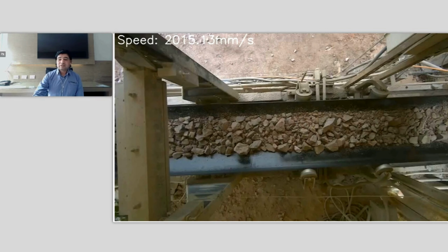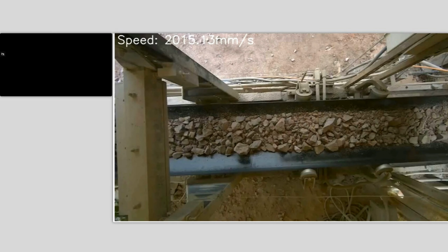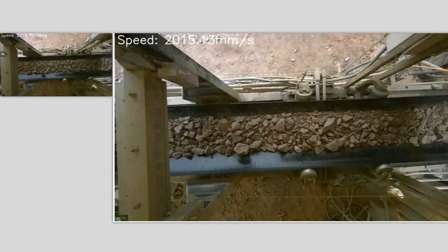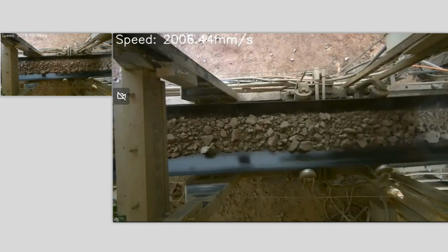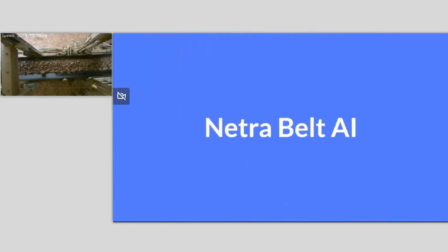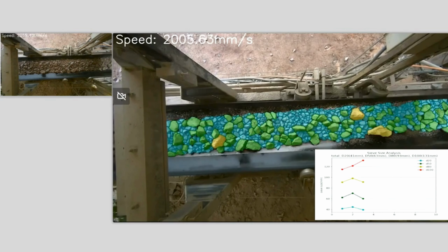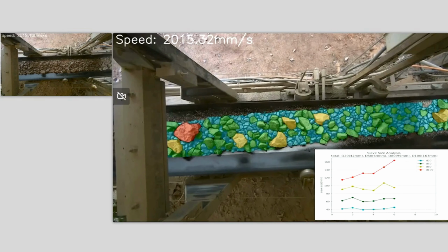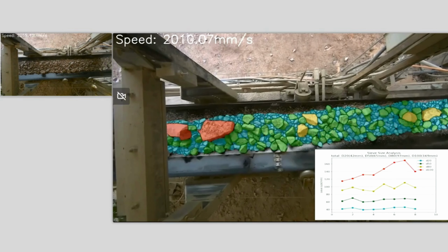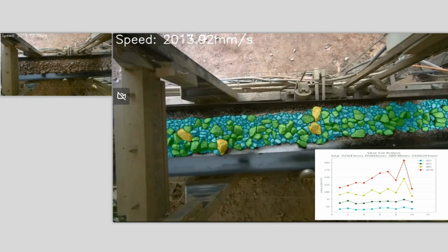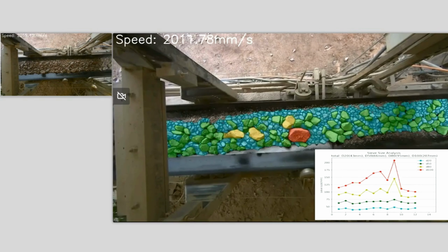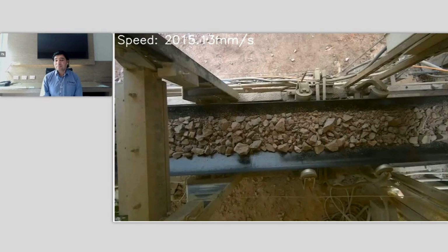And similarly, as we see on the belt as well, as each passing is happening on the belt, it's building a good understanding of what my size distribution is for the belt and the run-of-mill operation. So this information allows us to see if there are oversized rocks, as you can see, those are in red. That's not good for the operators here. So how do we build that alerting system? This can be integrated with the feed rate, or adjustments can be done for the plant settings.